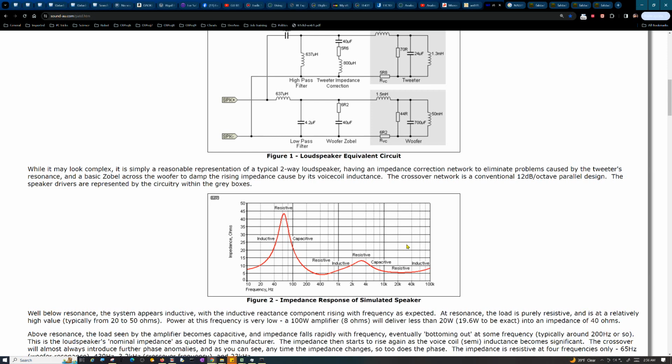They're from the days when they used MOSFETs as amplifiers in stereo equipment, which they do less today. Those were lateral FETs or something, I'd have to find it in the article. Those types of MOSFETs are more or less resistant to thermal runaway, just like you hear all over the internet. But these vertical FETs designed for fast switching apparently aren't as good at handling that.